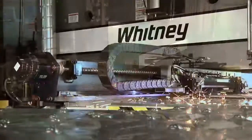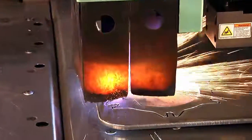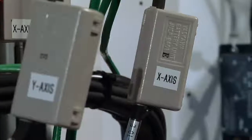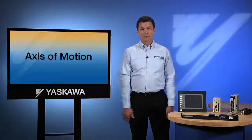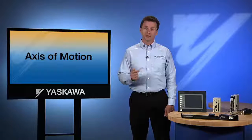In this example, the two axes are mechanically connected together to create two-dimensional motion. But even if there's no connection, each servo is considered an axis. Now this distinction is important because in the world of industrial automation, a single machine may have several servo axes, sometimes even hundreds of axes. Regardless of the number, there are some fundamental ideas that apply to each axis. And here's one of the most basic. An axis will provide no motion unless you turn the servo on.